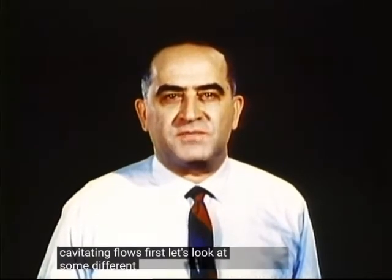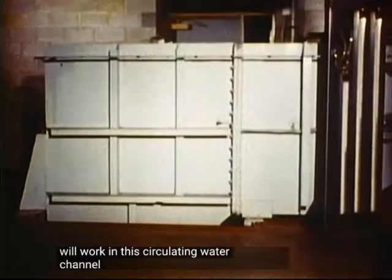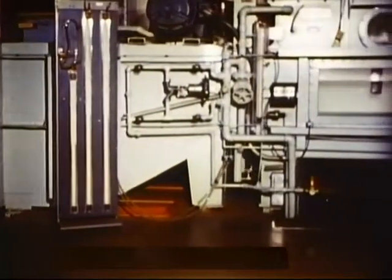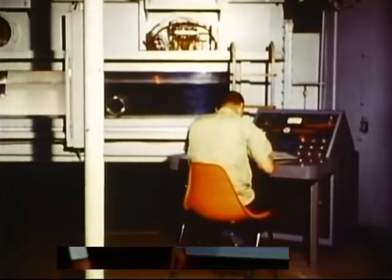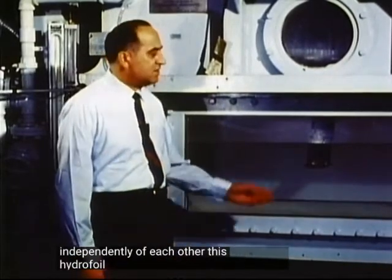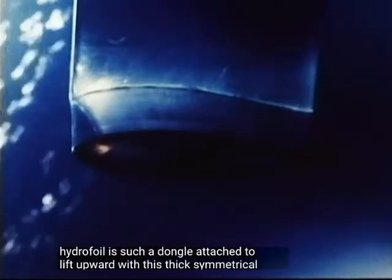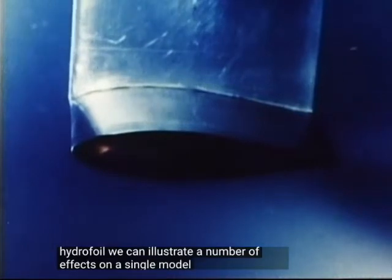First, let's look at some different types of cavitation. We will work in this circulating water channel. Here we can vary water speed and temperature and absolute pressure independently of each other. This hydrofoil is set at an angle of attack to lift upward. With this thick, symmetrical hydrofoil, we can illustrate a number of effects on a single model.